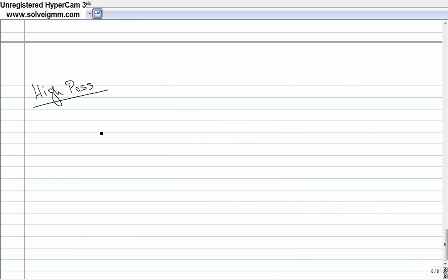High-pass filters. Now remember, order matters. I told you that in the circuit. Yep, drawing that backwards. Going on about order matters, and I can't get the order right. In this case, it's going to be capacitor first, resistor to ground. And then there's the output. Input, C, R.